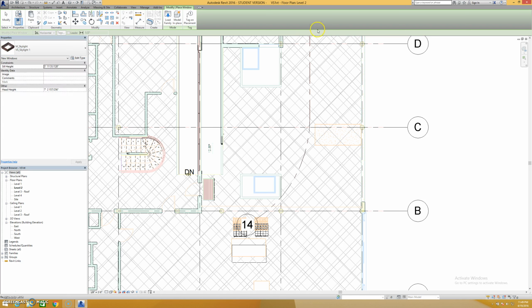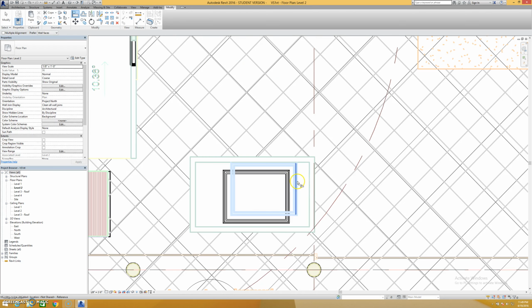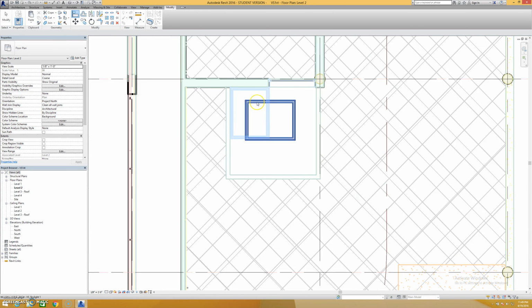They're just roof mounted or roof based windows. So here it is, the little skylight that came in with the project. If I just hover over my roof, I can place these skylights. And what's nice is I can kind of place them close and use the align tool to align these edges. A little bit easier that way, I think. Not quite aligned, but that's fine. And then we can use the rotate tool on this one.